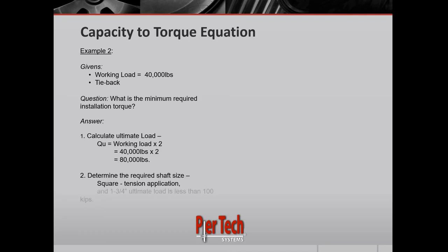The reason for that is you never want to design the pile to its absolute maximum load capacity. I discussed that a little bit in section 1, but you don't want to overload a pile to the point where you don't have additional capacity in case you need to get through a hard layer of soil, and you don't have any additional torque in your pile to do that.